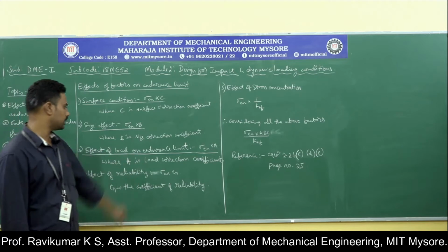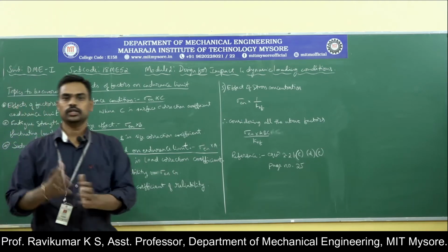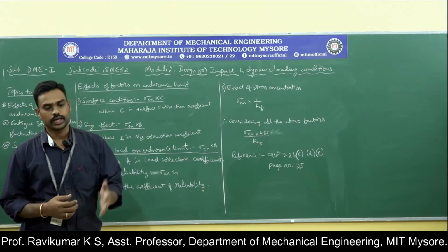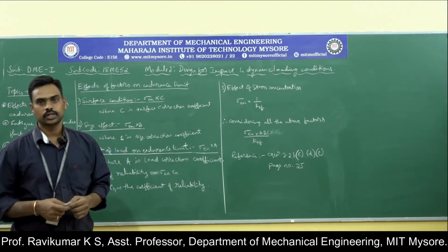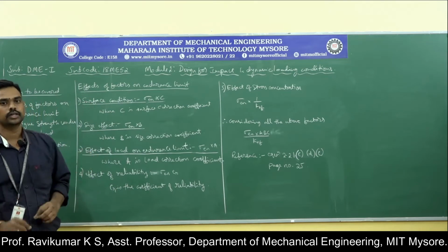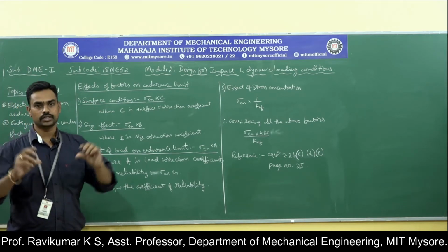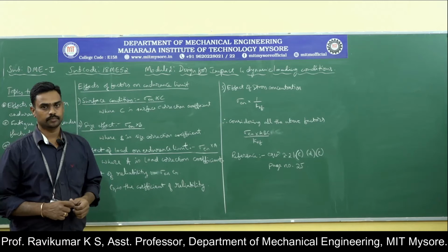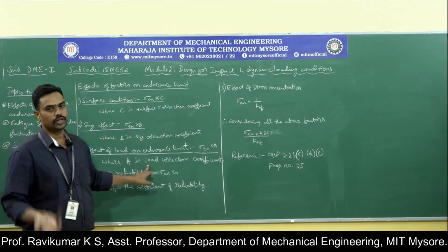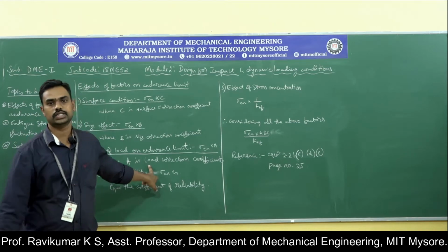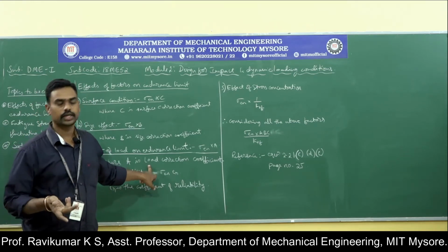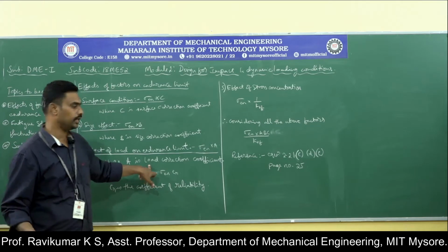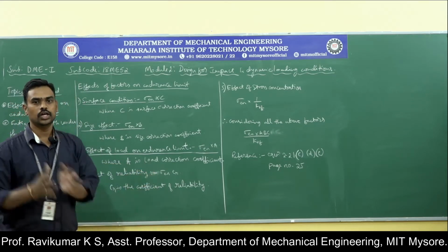Similarly, the effect of load on endurance limit. Again, for the fatigue strength calculation, there is a machine, something like a UTM, to calculate the fatigue strength of a material. Again, there is a standard specimen size. So you prepare a standard specimen and load it on the fatigue testing machine, and you test it for one loading condition. Only one loading condition. If the loading condition is different, say for example bending, or cyclic bending or reversed bending, or cyclic axial load or reversed axial load, like that, if it is varying, then again you need to correlate with the various loading conditions.